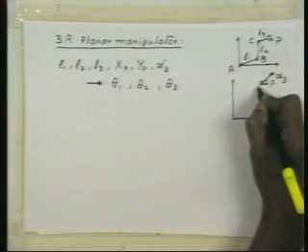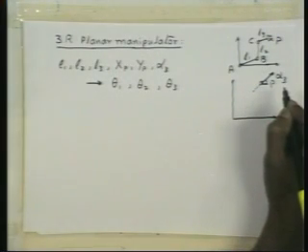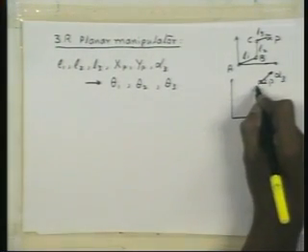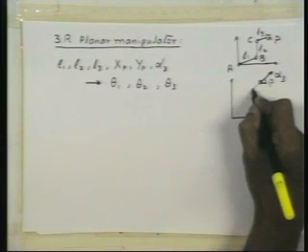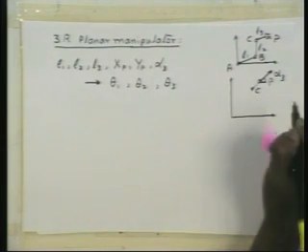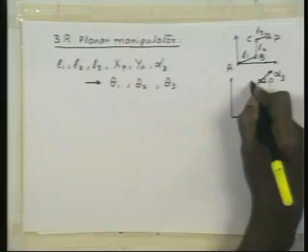This is the same as before. Did you hear that? The suggestion is that we know the position of P and the direction CP, right? With this information we can calculate the position of C. How do we do that? Geometrically draw this, extend this line backwards by distance L3. No need to cut an arc. Measure this out, so you get the point C, so that this distance CP is L3.